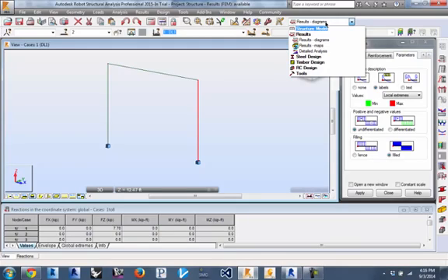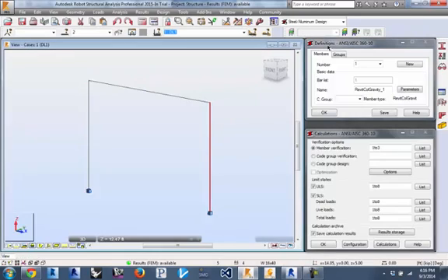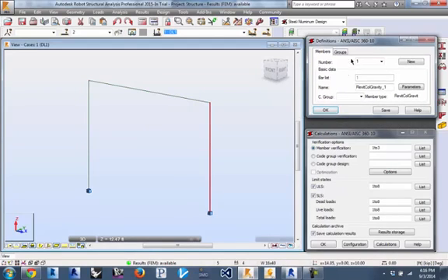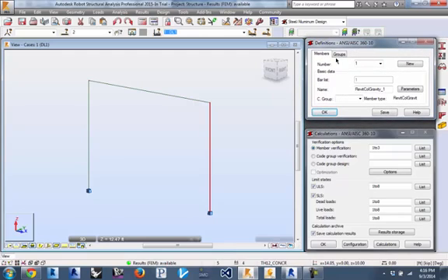on the columns. So in this, what I'm going to do is go to steel design and then steel aluminum design. And that flips us over to this view. And what we should see are two windows on the right-hand side. What we're going to do is create a group out of these columns, and then run the calculations on that group.